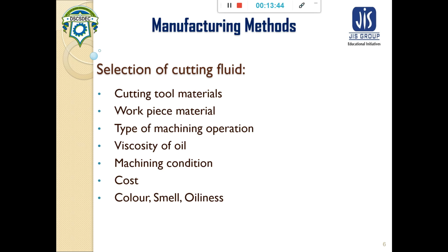But in other machining processes such as milling and drilling, using an insert tool or HSS tool, we put the cutting fluid, mainly soluble oil.